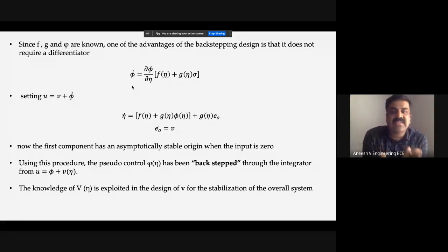In some cases, if our error comes to a constant term, the differentiator makes the system 0. We know that if you use a derivative controller alone in the system, we cannot use D alone. Why? Because if a constant error comes, the differentiator makes the system 0, and then the entire control structure comes to 0. That's the reason we also call the D controller anticipatory control. It will anticipate it at 0 and it will not produce any result.